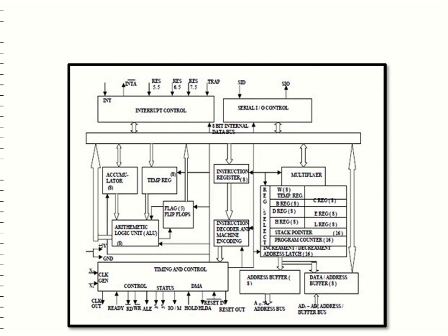Interrupt control. As the name suggests, it controls the interrupts during the process. When a microprocessor is executing a main program and whenever an interrupt occurs, the microprocessor shifts the control from the main program to process the incoming request. After the request is completed, the control goes back to the main program. There are mainly 5 interrupt signals in 8085: INTR, RST 7.5, RST 6.5, RST 5.5, TRAP.